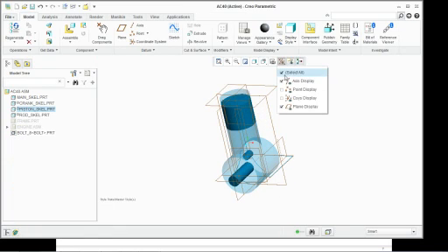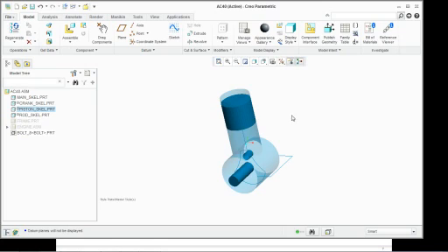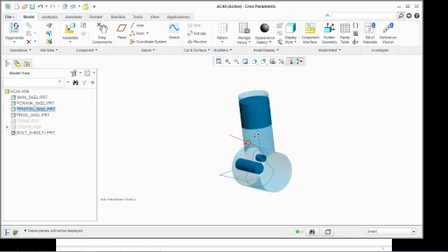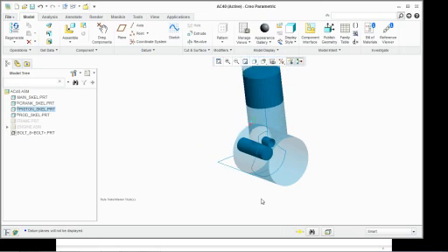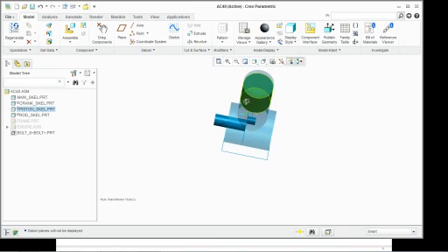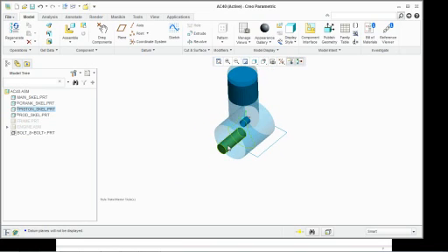So now I'm going to turn my planes off, my axes off, so you guys can see I've got a skeleton that's a realistic representation of an engine that we're going to build, and I can come in here and actually drag it through its full range of motion, and it will function the way that the final engine will. But I don't need to know all of the details of how parametrically to create the piston or the crankshaft or the rod. I just need to know roughly their lengths, that sort of thing, and I can create my assembly from this. So now you're saying, well, big deal, I can't give a skeleton to a customer. I need to create some solid geometry.